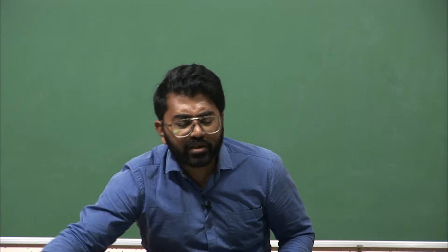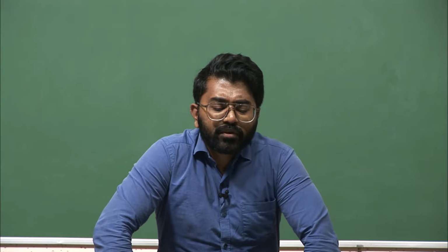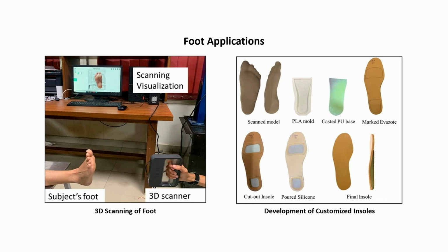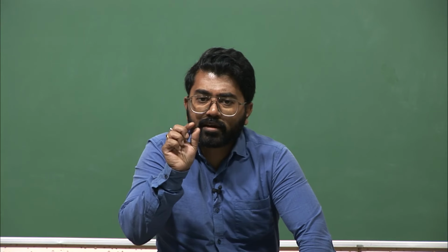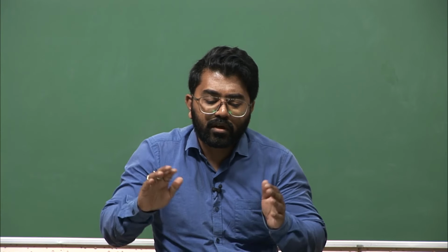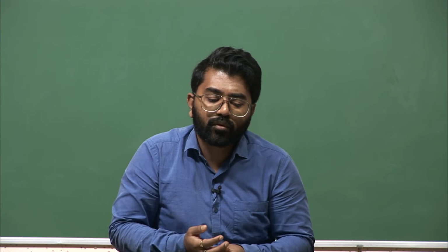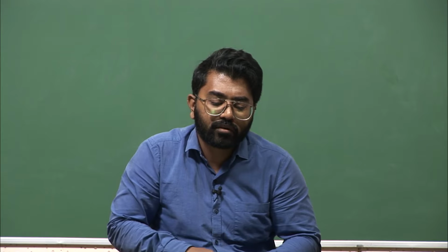So next, what you do is you place the scan model within a 3D modeling software like SolidWorks, and basically create a mold design around it. This mold design would be used for further casting of the different components of the insole, right? So you can easily trace, using some offset operations with a slight gap on the foot, the mold of half of the foot or 70% of the foot, which is what we did in this case.